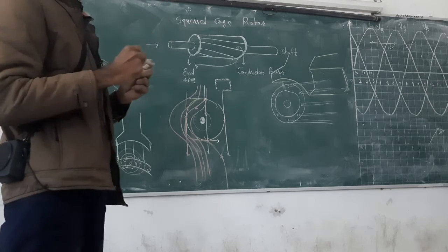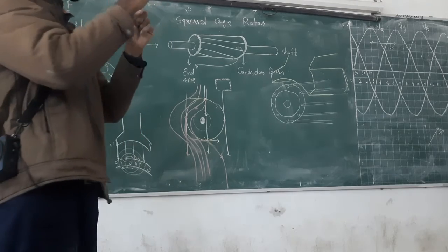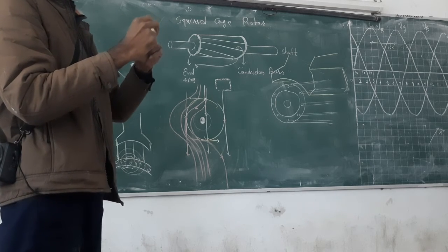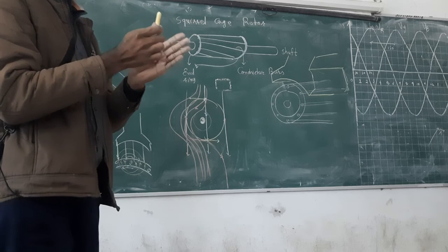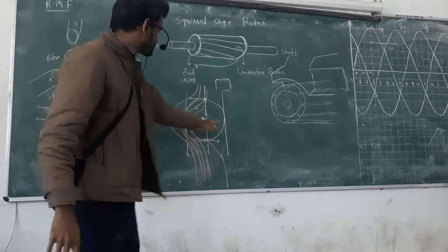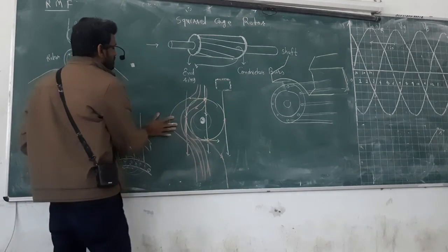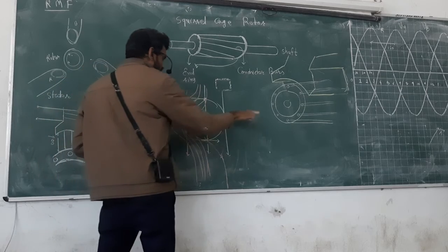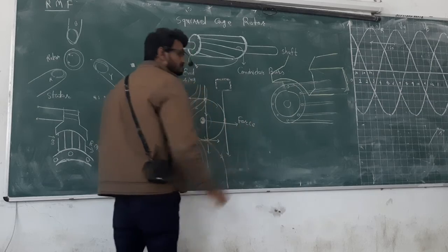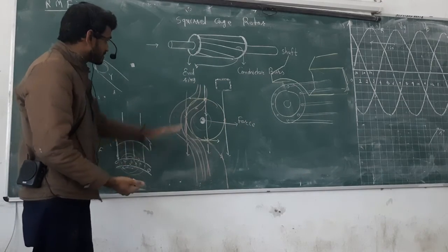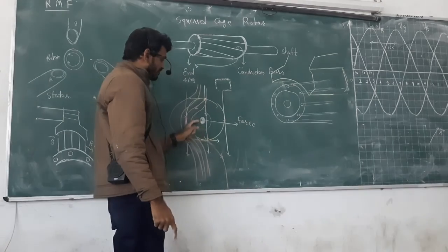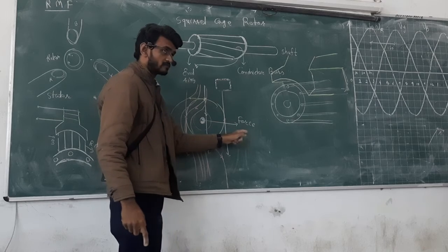So on the top the rubber bands are 2. At the bottom, the rubber bands are 0. So the rubber band will push from top to bottom. Okay, so the concentrated rubber bands or magnetic field lines will give the push on the material into the less concentrated magnetic field lines. So this pink concentrated magnetic field will give the force in this direction. Okay. The key thing is that this portion is rigid and this portion is movable. So the force in this direction, so the conductor will go in this direction.